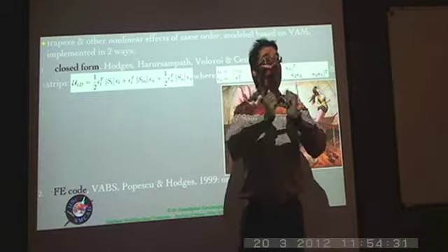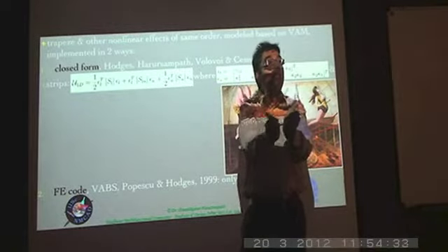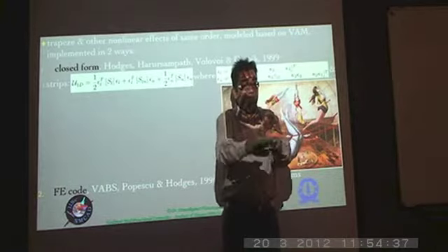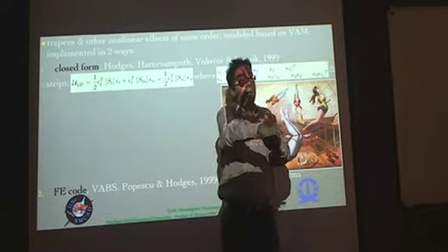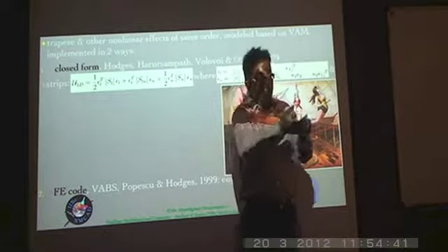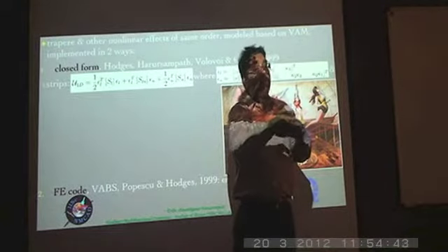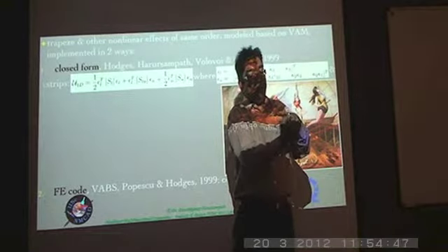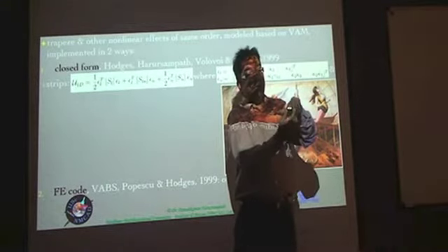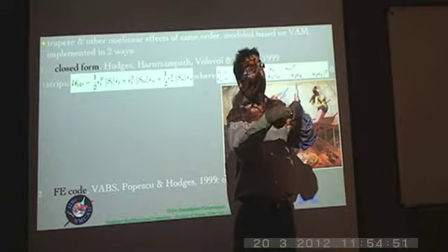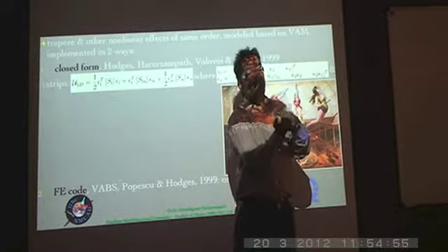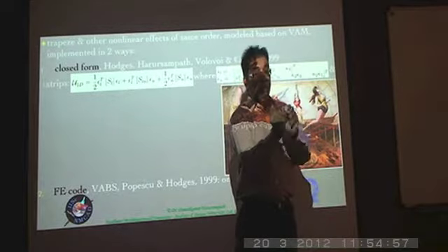One is about this direction, the other is in this particular direction. In this direction you see that it is very stiff because it has a much larger height, and you know that, to take a simple example of an isotropic material, the moment of inertia of relevance is h into b cube, whereas here it is b into h cube. So this is a much larger moment of inertia and therefore much larger bending stiffness, as you will observe